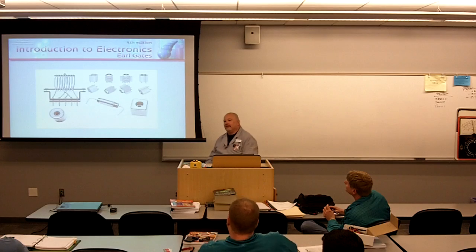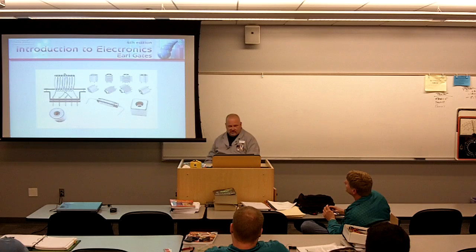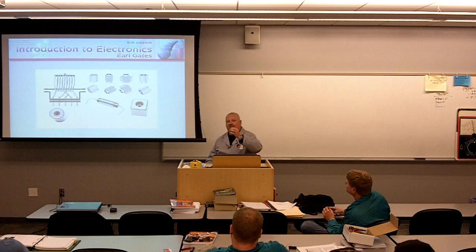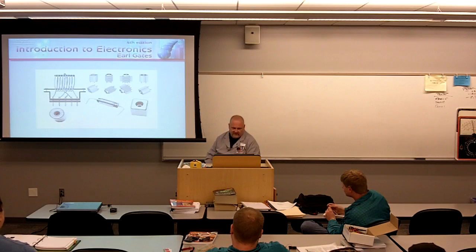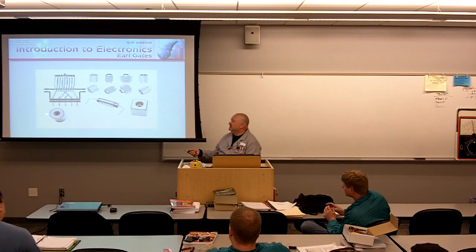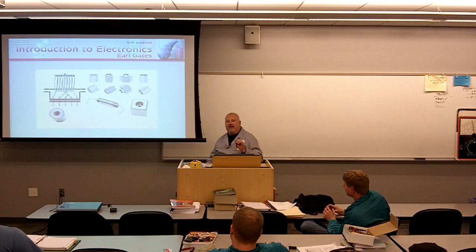Whatever you do, don't use an Allen wrench to try to adjust this. Typically the Allen wrench in your toolkit is made out of iron, steel, ferromagnetic material. So as soon as you get it in close proximity and you adjust it and get it just so, you're going to remove part of the magnetic influence and your numbers are going to go cattywampus. So all of these need to be adjusted with non-magnetic alignment tools.